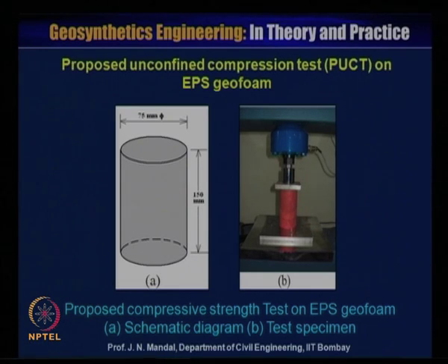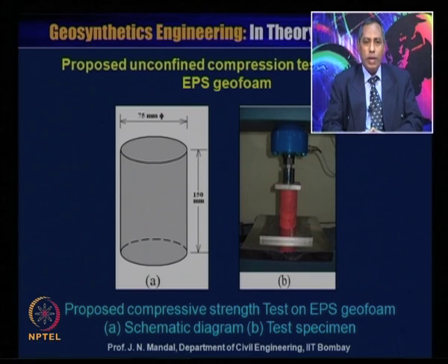So, here we are just recommending this proposed compressive strength test, and the specimen size is shown here. That is the schematic diagram of the expanded polystyrene geofoam, a cylindrical shape geofoam whose height is about 150 millimeter and diameter is 75 millimeter.